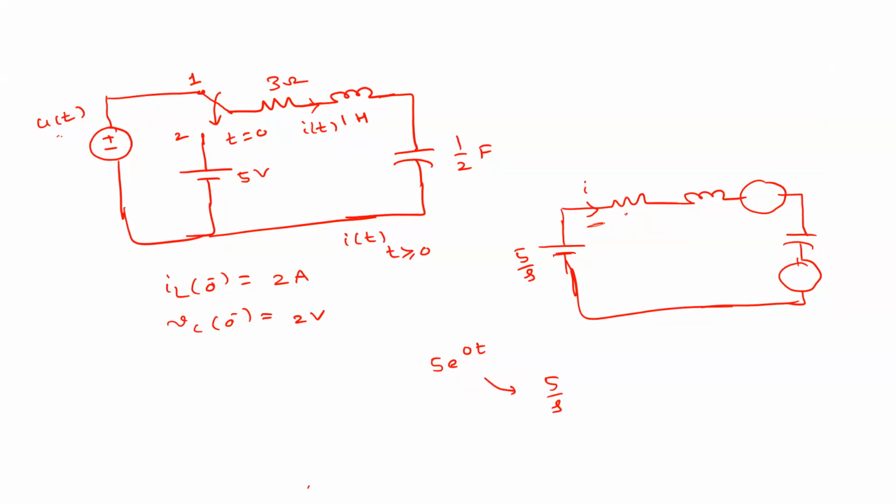So next step. What is this resistor? It is as it is, right? This is 3 ohm. So the inductor is s into L, so only s. Next come to this DC source. So how to fit this DC source? L into the initial condition, right?